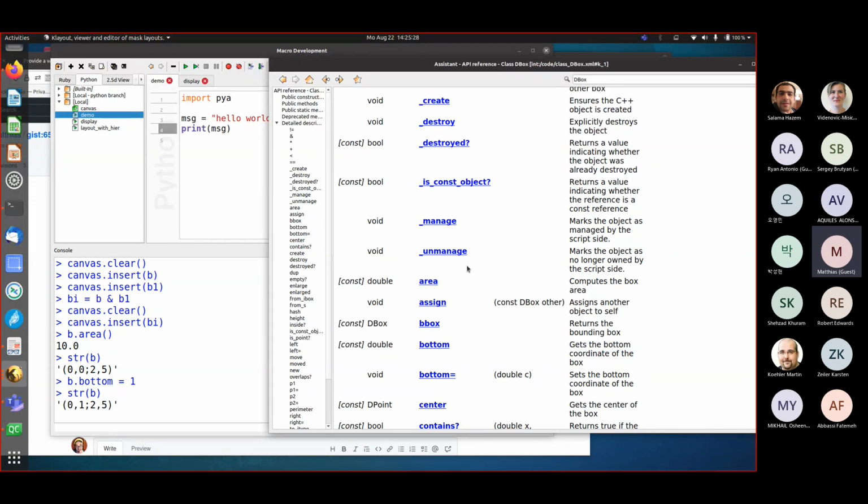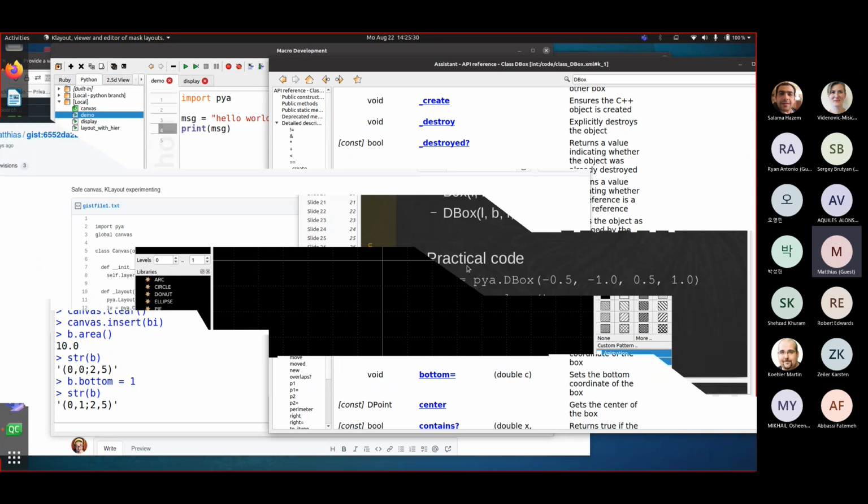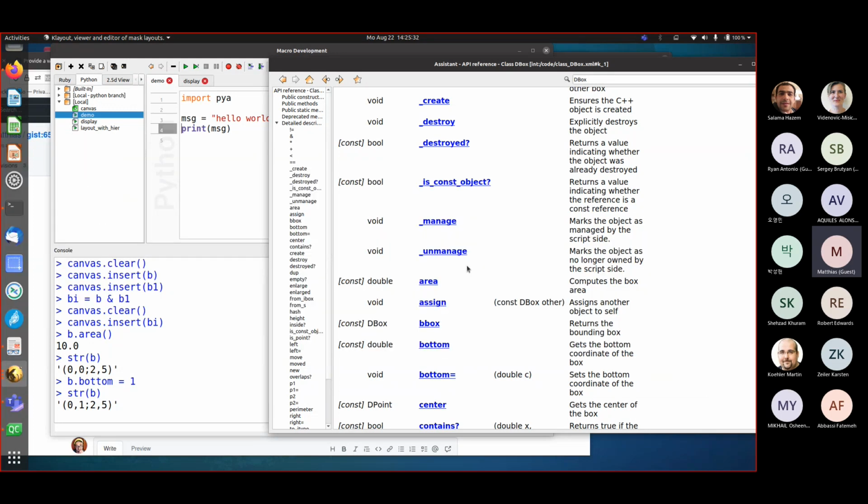Yeah, how can we put layer? Okay. First of all, it's just a box what we created now. What this insert, canvas insert does, it actually also already creates layer. Let me come to this later. I first would like to talk about the geometrical primitives. And the geometrical primitives don't have layers. They are just the boxes, right. And we will then build layout from that. This is how it's done in KLayout.